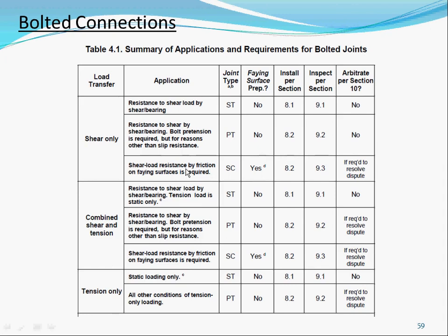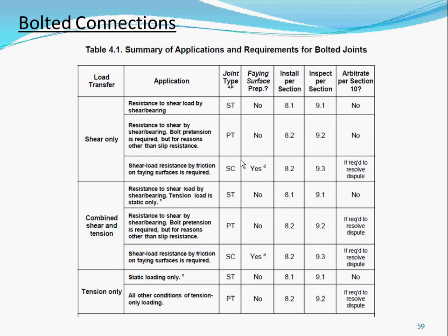We're not designing that for that. So our joint type is not slip critical, it is pretension, and because of that, we don't need to prep the surface. Either way, we are sticking with the pretension joint, but no surface preparation.